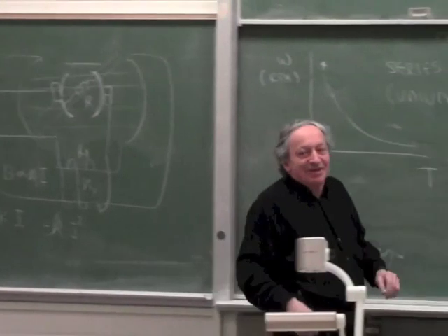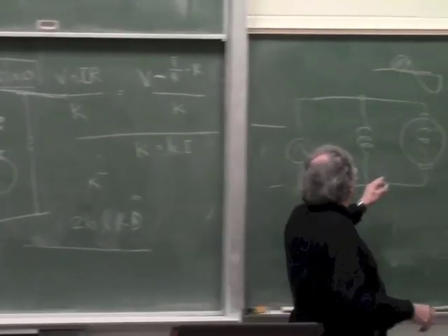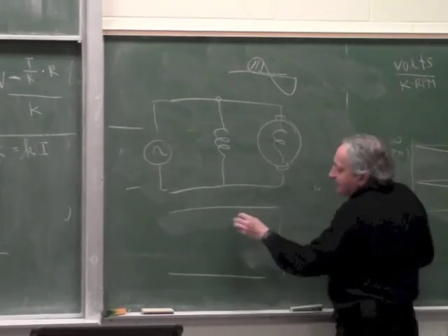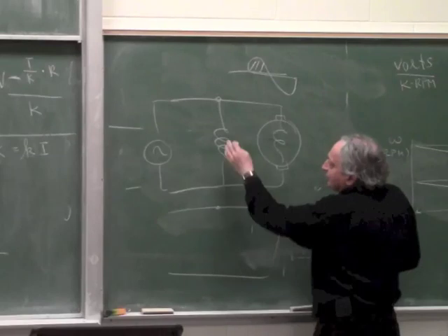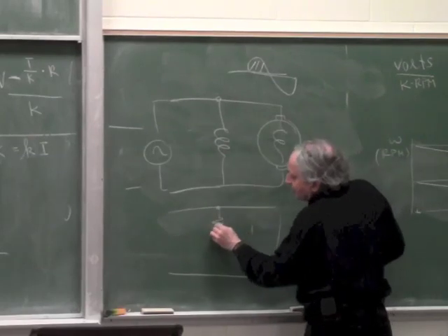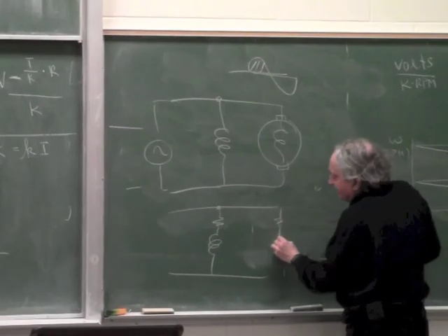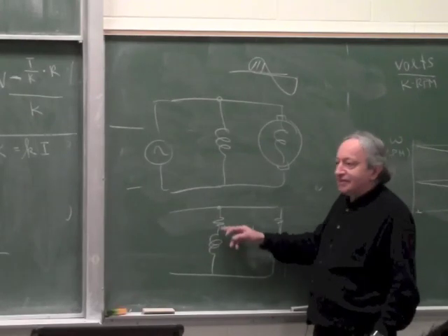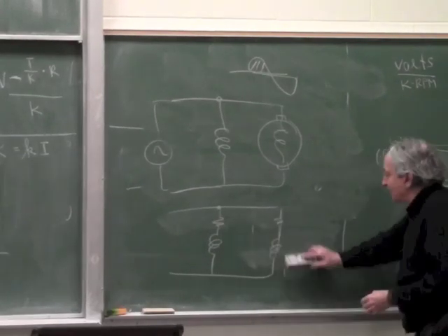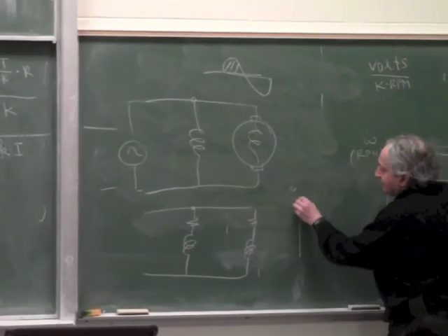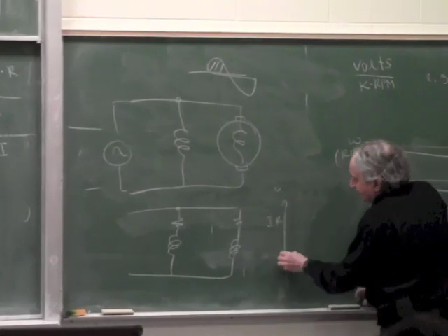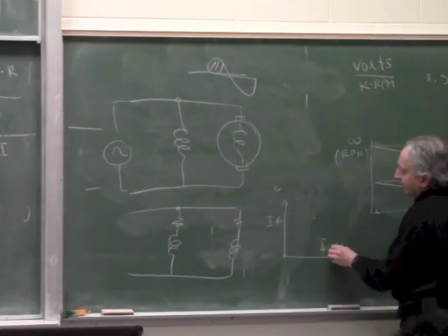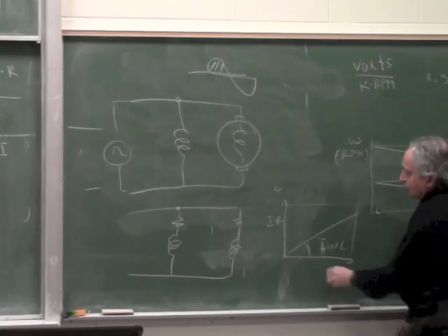See, good. Because when you have two inductors, and the two inductors have resistance, this is the DC model. But if I draw the AC model, if I don't just look at the currents, but I look at the phase shift, each one has a resistance and an inductance, but the exact phase depends on the ratio between inductance and resistance, because if you recall from electrical engineering, there is IR and there is j omega L, or I omega L, and the resultant vector is actually the phase.